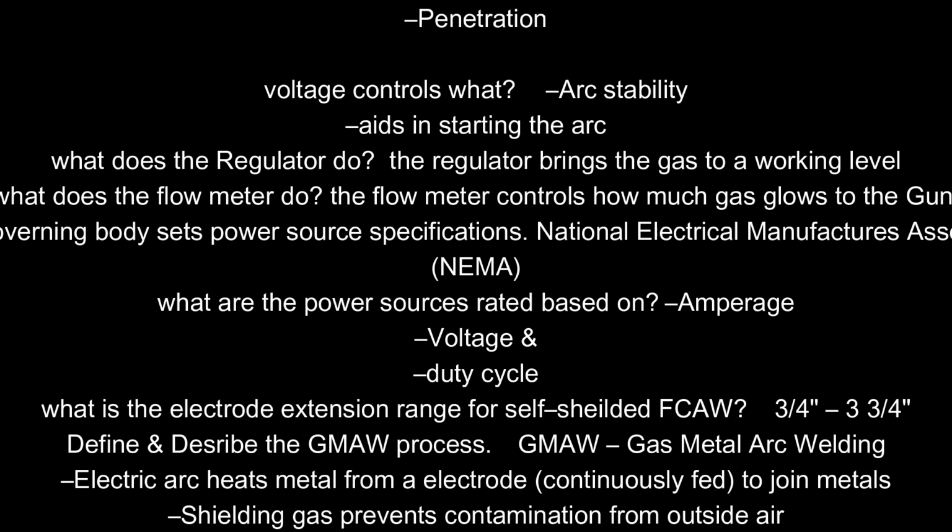What does the regulator do? The regulator brings the gas to a working level. What does the flow meter do? The flow meter controls how much gas flows to the gun. What governing body sets power source specifications? National Electrical Manufacturers Association, NEMA.